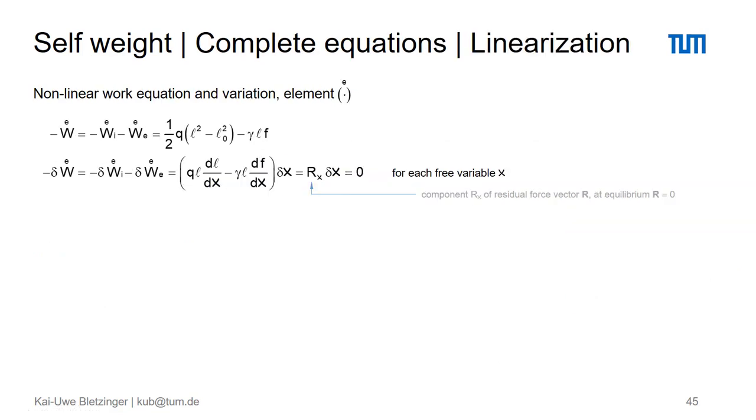Now we can just put everything together. The contribution of the element with respect to the work, or negative the energy, is the inner energy and the external energy. The inner one just comes from our force density expression, as we have discussed before. And here that's the contribution of the self-weight in terms of the weight and the center deflection of this element.